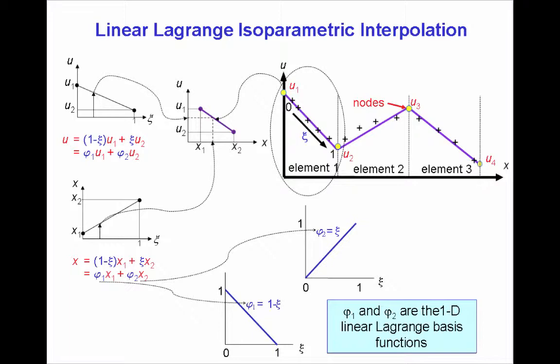Note also that the term isoparametric here refers to the fact that rather than interpolate a variable y as a function of geometric variables x, we interpolate both as functions of xi, so that y of x does not itself need to be a function. The major advantage of finite element basis functions, such as linear Lagrange interpolation schemes, is that, since the parameters of the interpolation are the value at the global nodes shared by adjacent elements, continuity of interpolated variables between neighboring elements is automatically ensured.